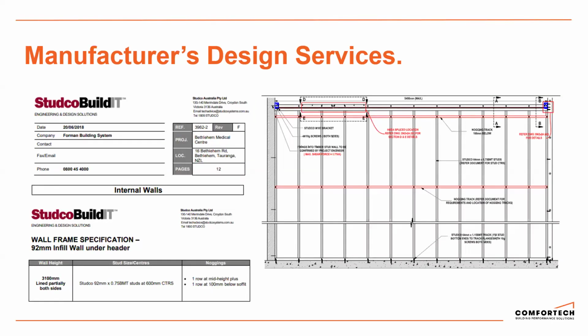So one way to get a more specific design in terms of partitions: we've got our standard design table, so the next step up from that is to use our manufacturers. Most manufacturers have an engineering team. So we can send them through a full set of plans with the information, with the location, and basically they'll design the partitions and produce a document. This document will tell you the wall height, the stud size, what centers they need to be at, how many nogs they need, what your fixings need to be for each type of wall in your project. So this is a free service.